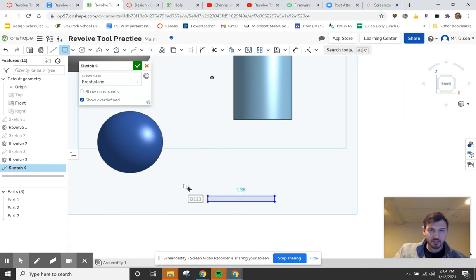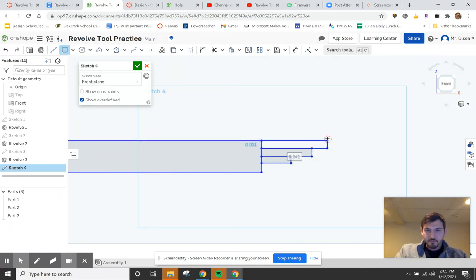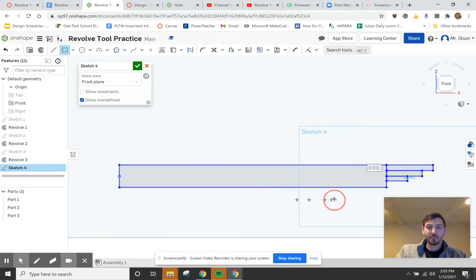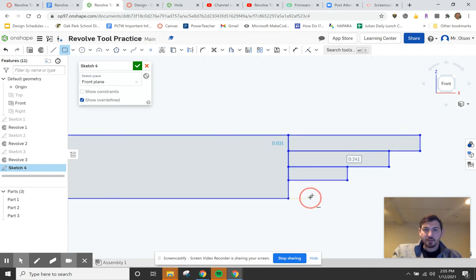So when I revolve it, it's just a rectangle, right? So it's like a thin cylinder. But to make it look more like a plate, if I were to zoom in really close, I can give it ridges. Maybe something like this. Okay, so that will help make it look more like a plate. The other thing I could do later on is fillet the edges to make them smooth, more like a plate. But for our purpose, I'm just going to keep it simple here.